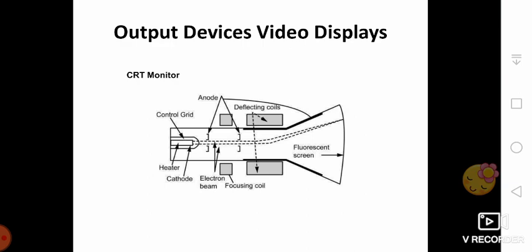The number of times in one second that an electron gun redraws the entire image is called the refresh rate and is measured in hertz, cycles per second. In a common technique, particularly in lower-priced equipment, all the odd-numbered lines of an image are traced and then all the even-numbered lines. The circuitry of such an interlaced display needs to have only half the speed of a non-interlaced display.